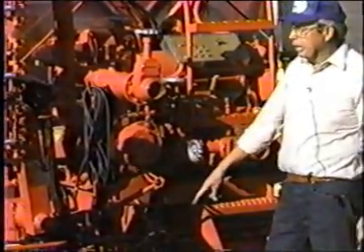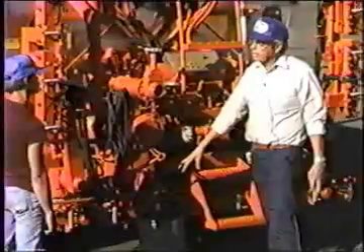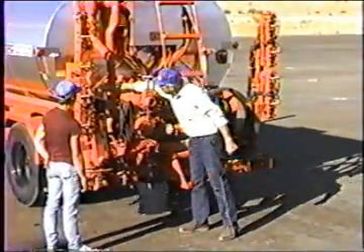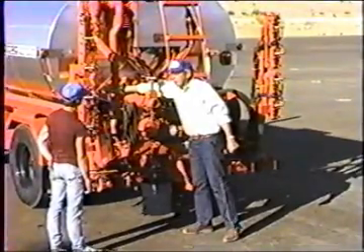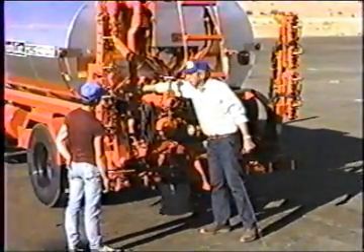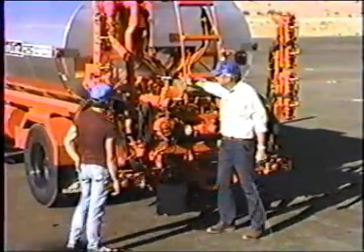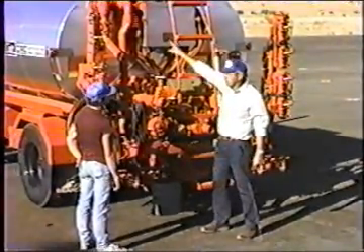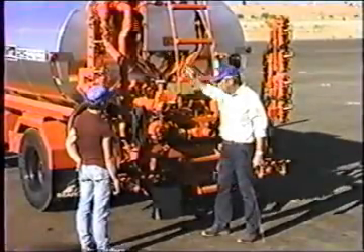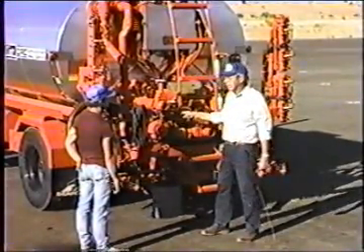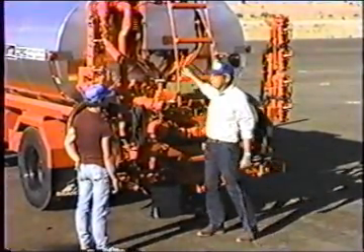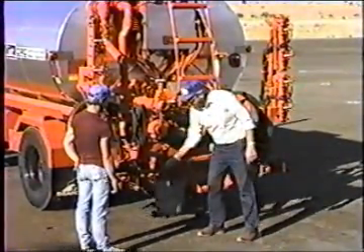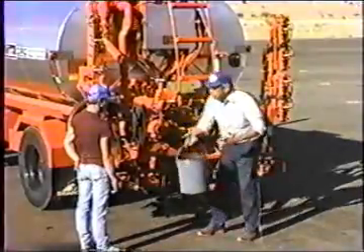We're still circulating the bucket. We've got to do something with that diesel in the bucket. The easiest thing is to close off the return hose to the bucket first. Close that valve. Put the rear master switch back into the on position, and that relieves the air pressure from the relief valve. Now the material is just being pulled out of the bucket, circulating and going right back in the tank. When the bucket goes empty, drain it out good and take your bucket, put it away.